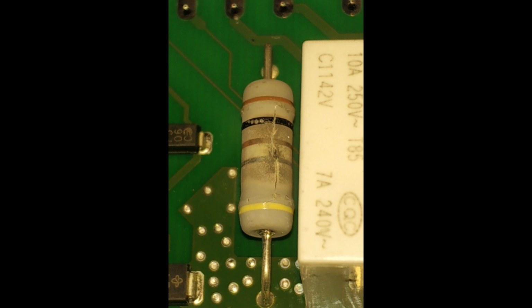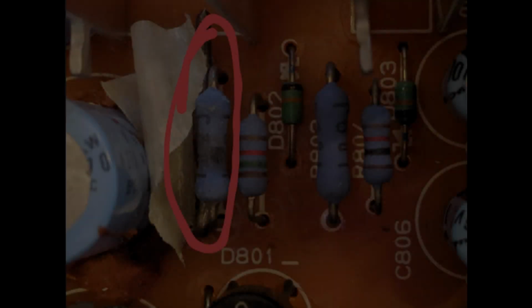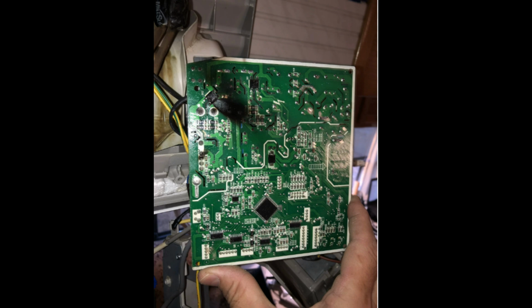Why resistors are important: protecting components. In electronics, many components have specific current or voltage limits. If we exceed these limits, the components might overheat or get permanently damaged. Using a resistor is a way to protect them, especially when using something sensitive like an LED.